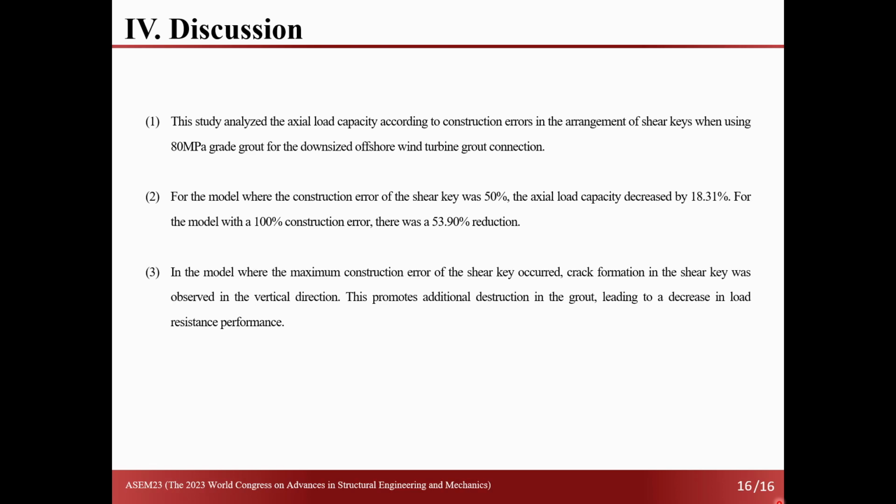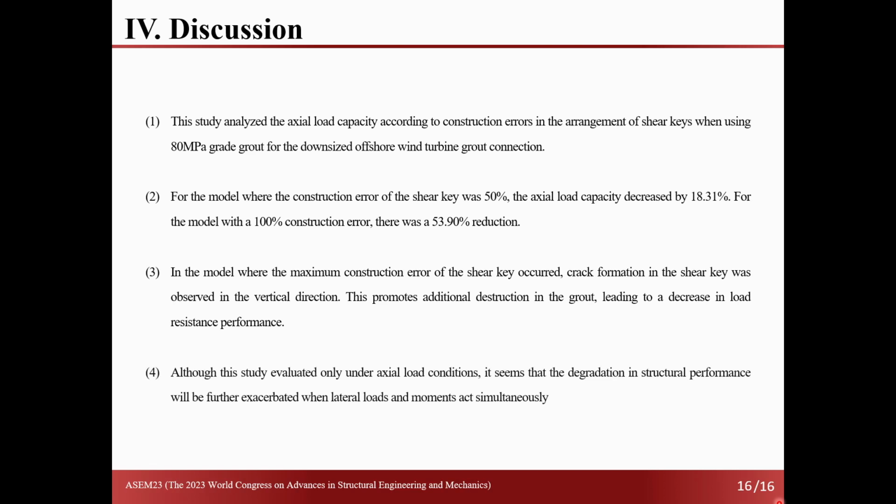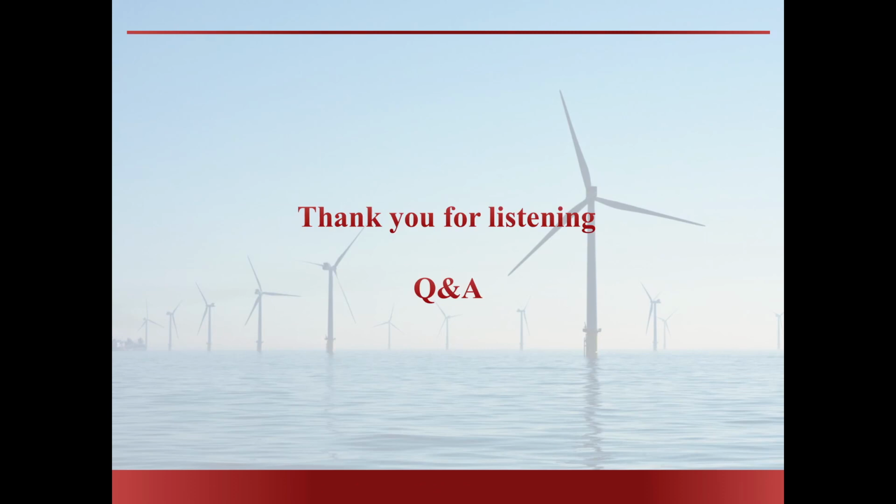In the model where the maximum construction error of the shear key occurred, crack formation in the grout was observed in the vertical direction. This prompts additional destruction in the grout, leading to a decrease in load resistance performance. Although this study evaluates only under ultimate load condition, it seems that the degradation in structural performance will be further exacerbated when lateral loads and moments act simultaneously.